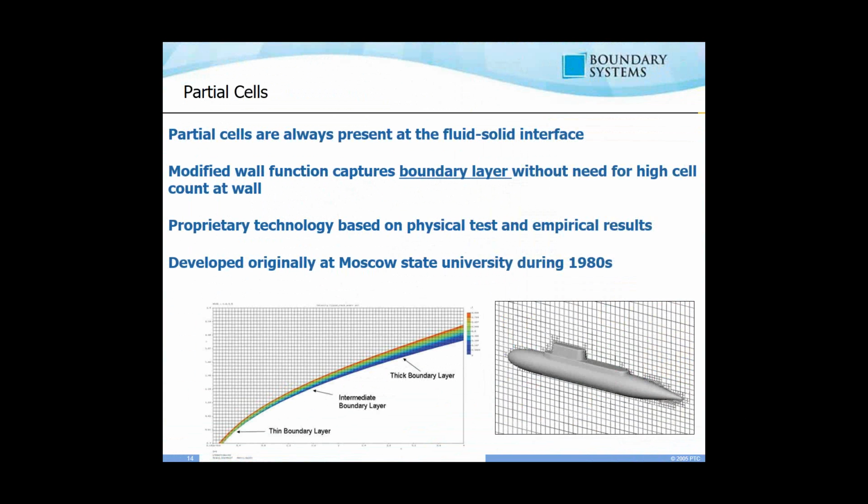So typically within one smart cell, you can capture the physics inside of a boundary layer, regardless of if the boundary layer is thin or thick. FloEFD smart cells can easily help capture that physics very, very accurately. And there are many examples where FloEFD is compared to real-world tests and also other CFD codes as well. And it's always very accurate in how it predicts the flow, even in boundary layer driven flows.